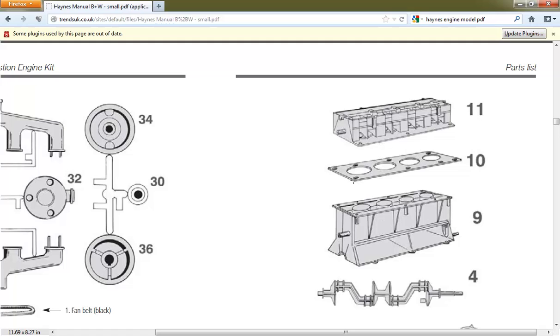And I think it's safe to assume that the width of this gasket is exactly the same as the width of this face here, and so is this one. So in order for you to save a lot of time measuring the details over and over again, I want to show you there is a quick way of doing this in Solidworks. If you measure one of these parts, for instance the gasket, you can use that as a base layer to produce these two parts, because they are all related. And if you make a change to one of these, they're all going to change. Or if you make a change to the gasket, it should all have a linear effect on the other two parts.